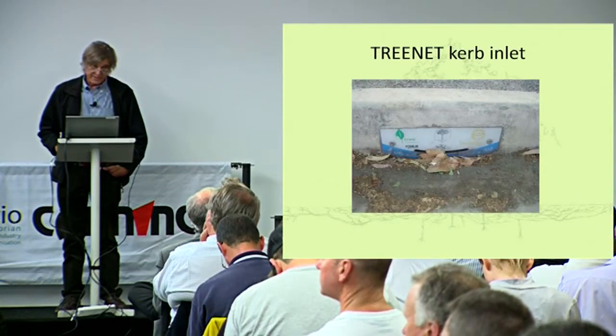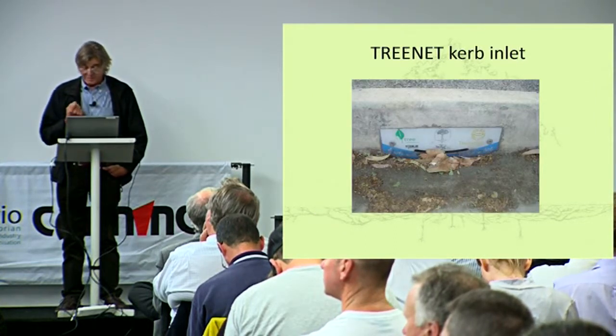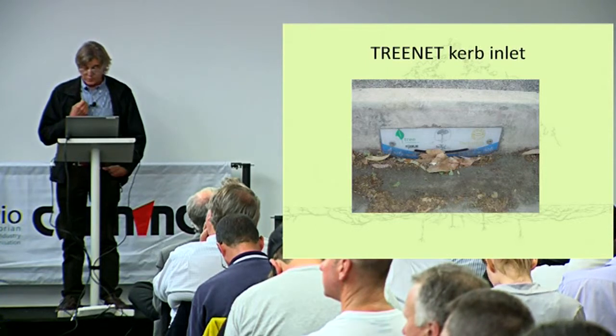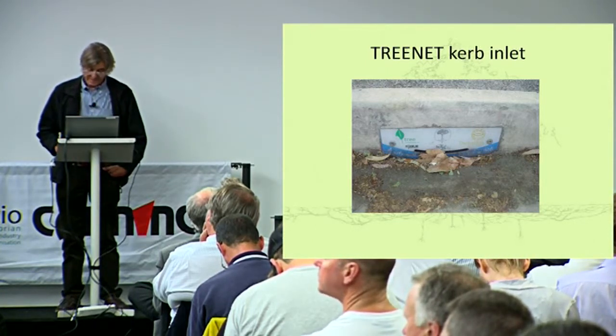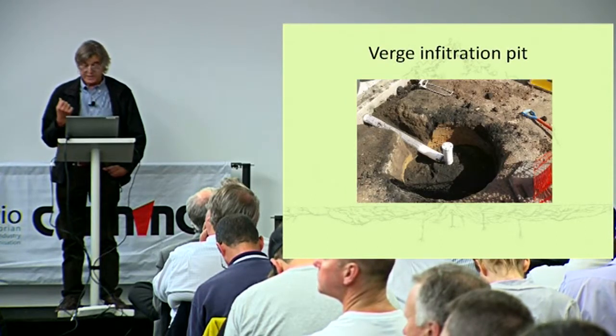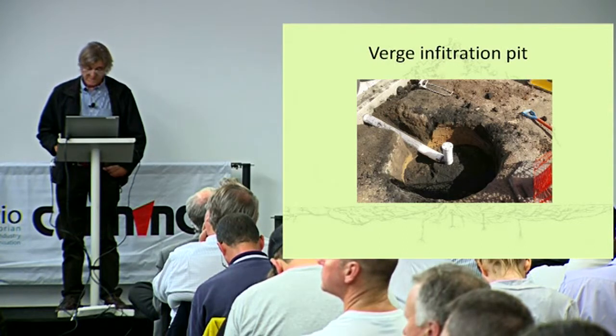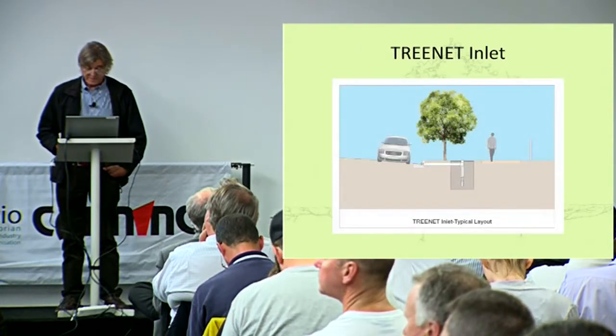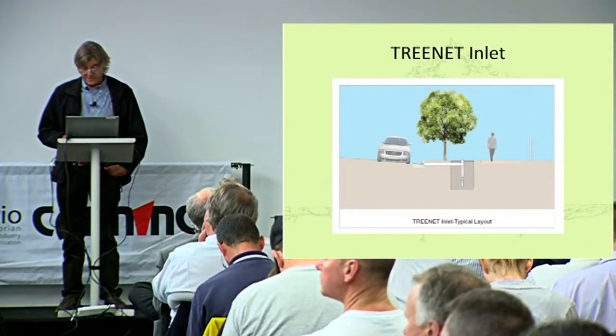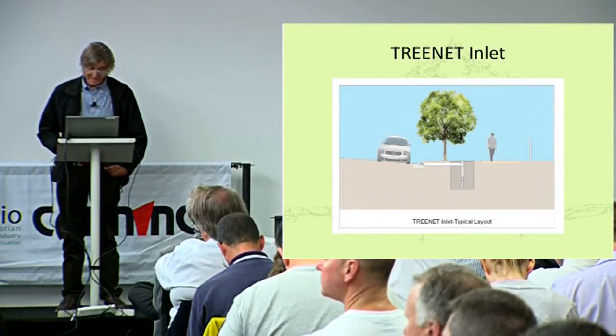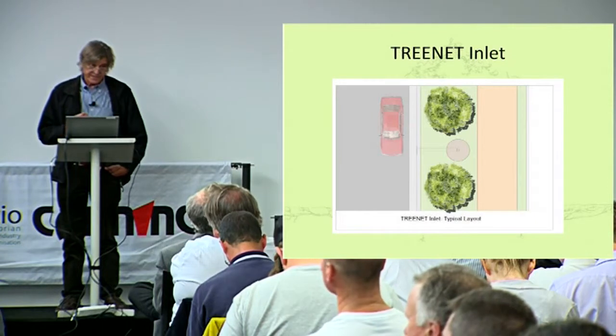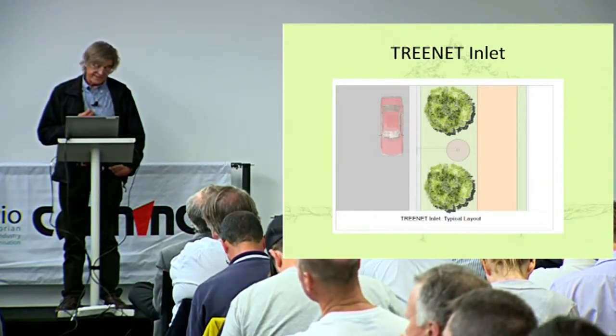So that's the inlet itself, which is designed to capture runoff without becoming clogged. And that connects to an infiltration pit in the verge. Here's another view of the system, the inlet connecting to the pit in the verge. And these can be retrofitted into streets between existing street trees.